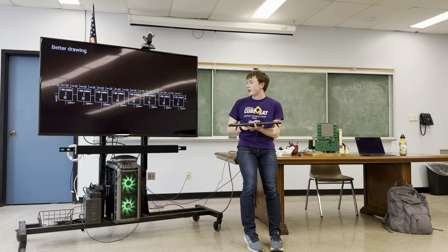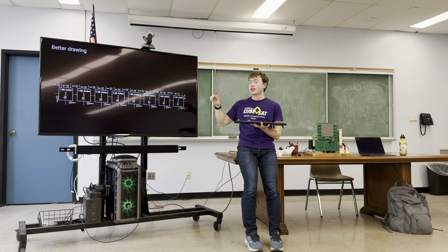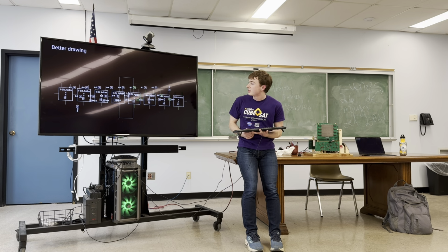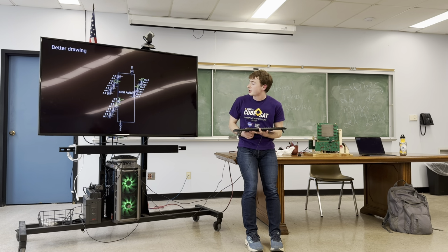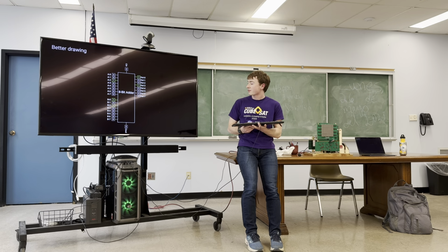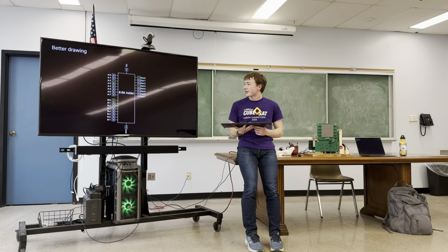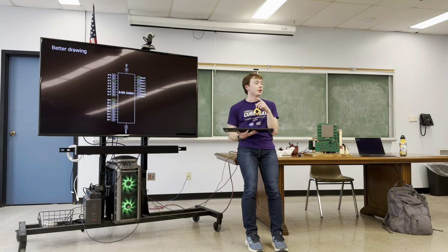And then a better way to represent it, with all the 2 input numbers grouped together. I should not have done that. And then, yeah, it looks cooler when it's looking better. That's one basic piece of a computer that can be used to do that. It's also possible to do subtraction if you bitwise invert the second operand and then add 1, which you can do by setting the carry input to 1.